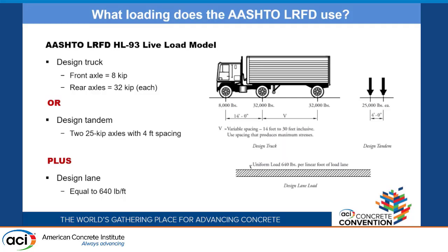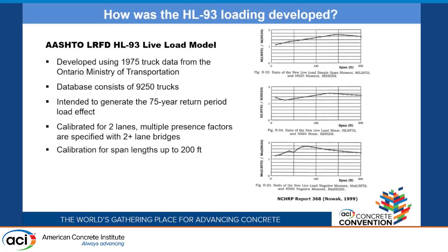All right. Or a design tandem, which is 25-kip axles with a 4-foot spacing. And then finally, that's combined with a lane load, which is a uniform load across the entire lane or portions of that lane that maximize the effect.